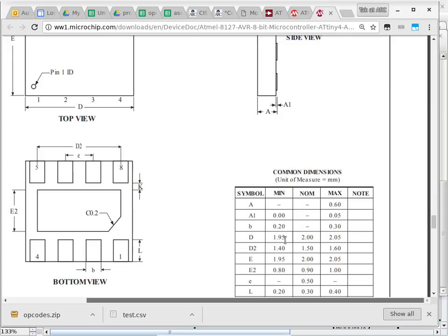Do you think we can put one of these things into a wrench? Why would I put one of these things into a wrench? Yep, exactly. I want to know how much torque is applied. Okay, and these things can do it. You just need a Bluetooth chipset to go with it, and then your phone can display how much torque is actually getting applied. Or you can pre-program the torque range and say, if I get to this amount, you'll beep me, let me know that I'm in the right range, and when I'm right at the right value, you'll give me a long tone so that I know when to stop.